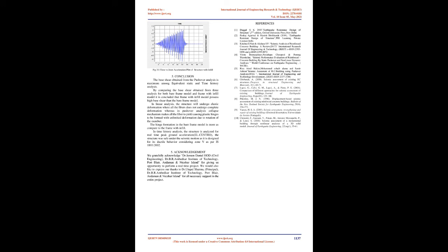In time history analysis, the structure is analyzed for real-time peak ground acceleration, El Centro. The structure was safe under the seismic motion as it is designed for its ductile behavior considering zone V as per IS 1893:2002.